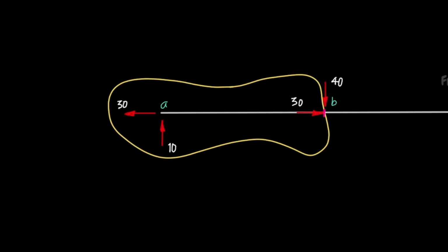Why? Well, it's suboptimal because although it will tell us about the bending moment at B, it will tell us nothing new about the axial force and the shear force. We know that axial force and shear force are constant between point loads, hence the axial force and shear force just to the left of B will be plus 30 kilonewtons and minus 10 kilonewtons respectively, exactly the same as at A.